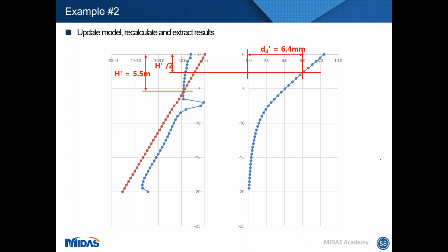It's just calibration of this parameter for the springs, for linear springs, with some pile tests and some previous experience on site. And then, since they are linear, you will always have compatibility within the stress and deformation.